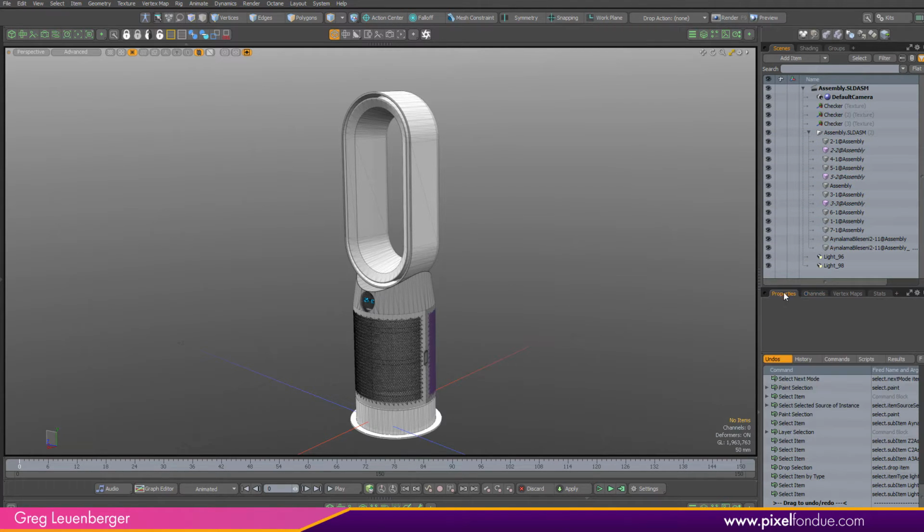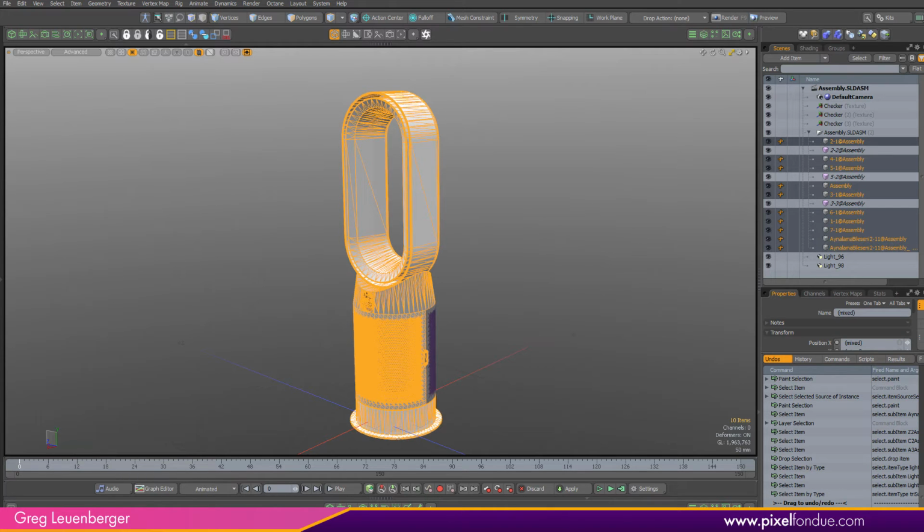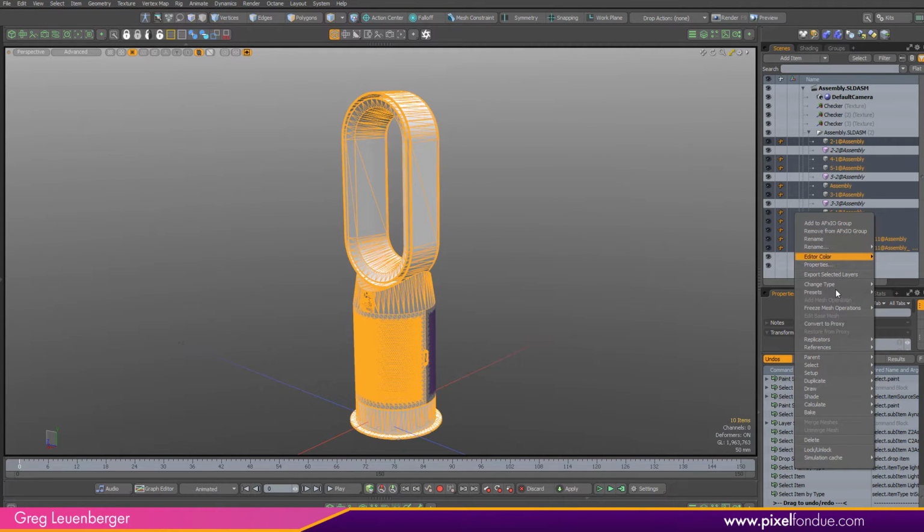So here we have select.itemType, space, and then you just type triSurf, with a capital S, like that, and hit enter, and it'll select all your static meshes. Sometimes you may have a list of 100 of these things, so it's good to know that command. Here I made it into a macro where it'll do that. It'll select them all, and then it'll convert them for me if I just go to change type and go to mesh.